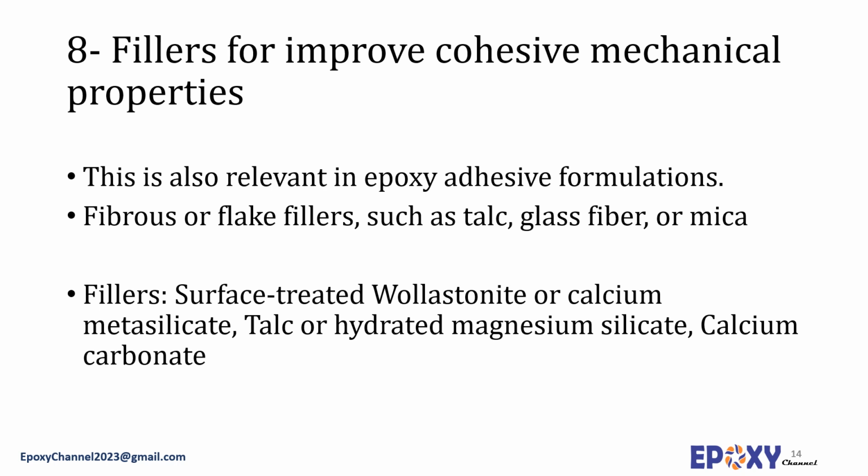Particulate fillers usually reduce tensile and flexural strengths. Impact strength is generally adversely affected by the particulate fillers. The addition of particulate fillers generally decreases compression fatigue but increases ultimate compressive modulus and compressive yield strength because of a stiffness effect. The reinforcement of epoxy adhesive has typically been achieved through the use of fibrous and flake fillers.